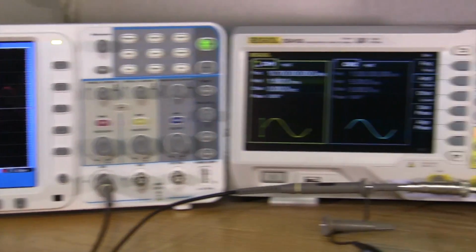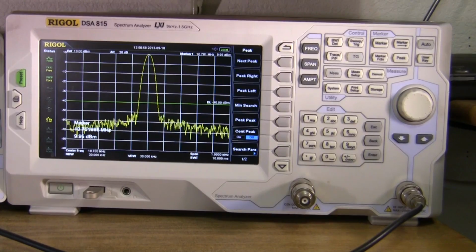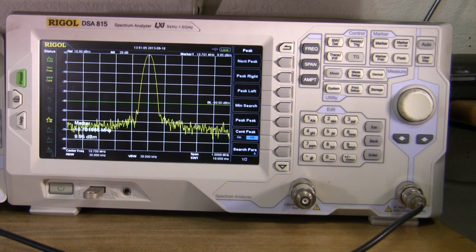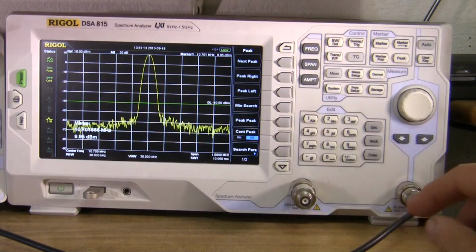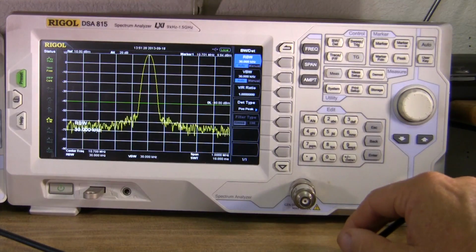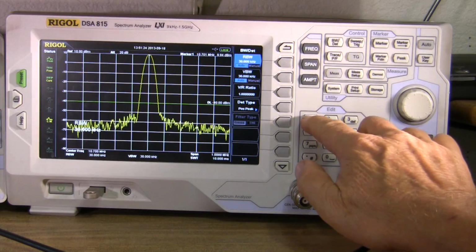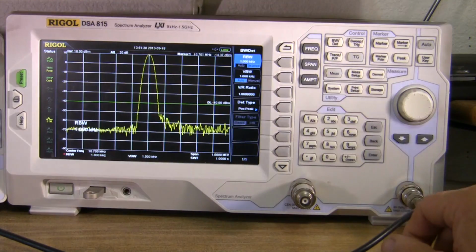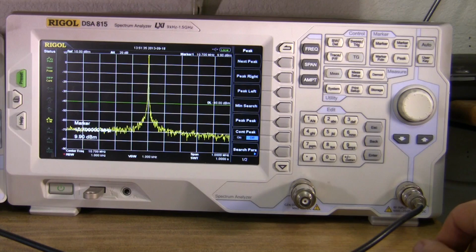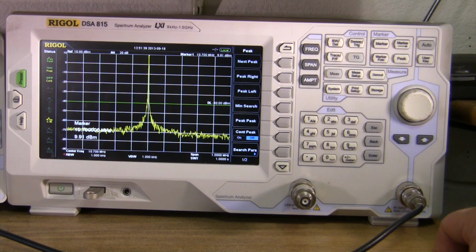But of course, the spectrum analyzer, which has a little better time base, says that it's 10.70168 or 666. Now I can probably improve on that a little bit, because this, of course, doesn't have a very sharp nose on it here. So if I go to the bandwidth here and change it from 30 kilohertz to say 1 kilohertz, now I have a very sharp point. And if I hit the peak on that, it's going to tell me it's 10.7000000. That's a little bit closer to the reality that I'd like to see. And so it's quite accurate, obviously.